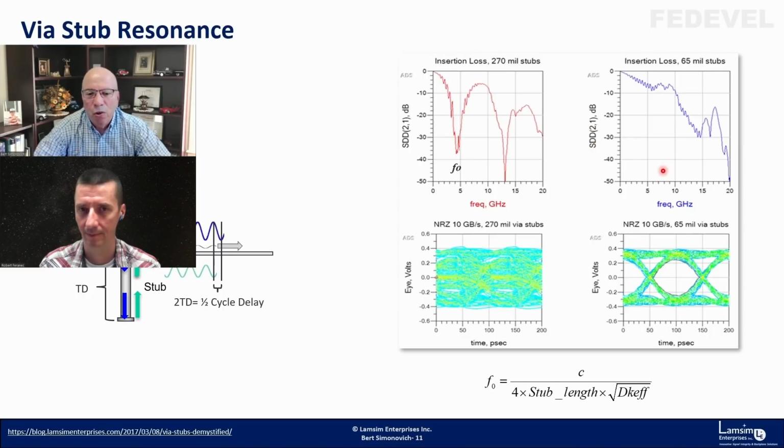If you have really good material and have done your homework and good design, it might be around 30 inches at 10 gigahertz, for instance. At 28 gig, it's probably less in length, right? It's really the loss.